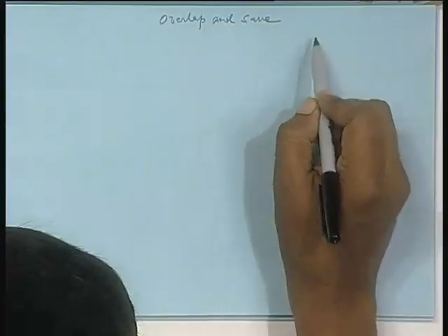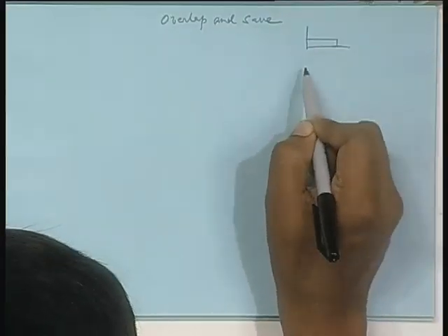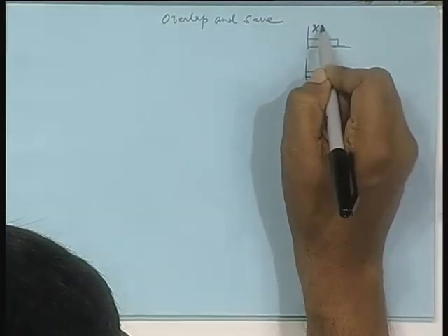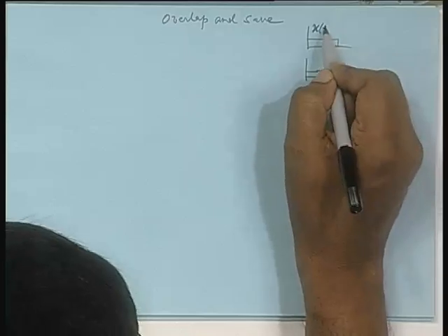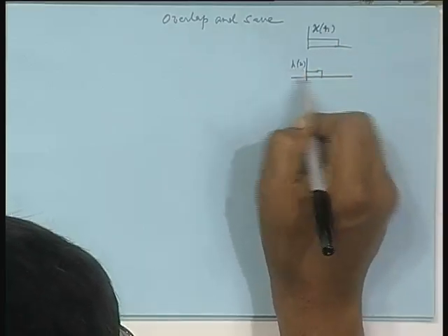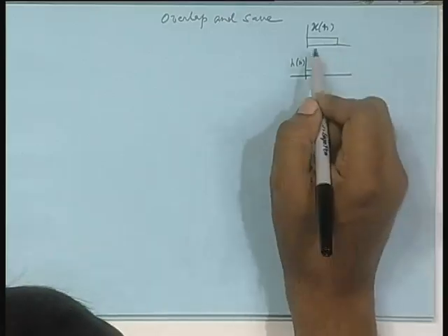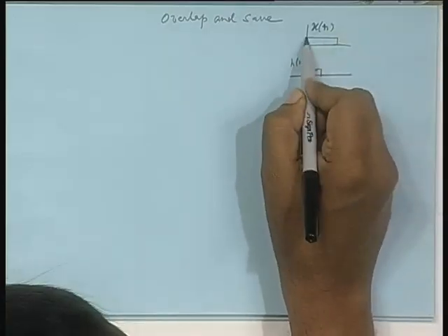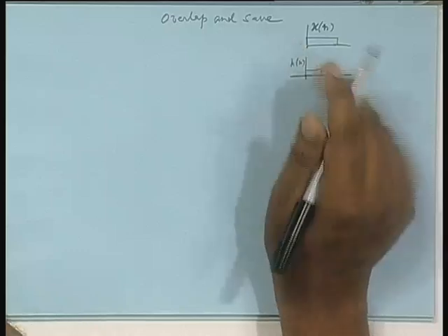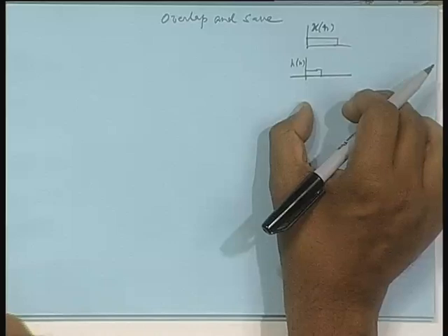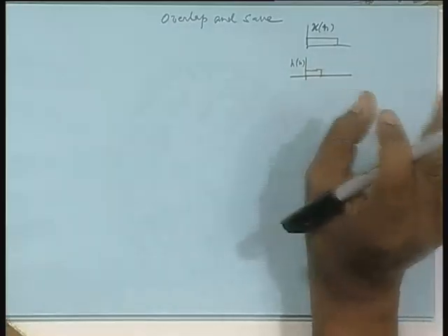Firstly, before I go into that, certain basic things of DSP, you see whether you can foresee. Suppose there are two sequences, one is here, another is here. You call it say x n, and you call this h n. You get a convolution. See, I have drawn it like this, that is causal. It is not necessary that they have to start at the origin, they can go beyond to the left also. My result does not depend on this shape, just two sequences. If you convolve, you get something. We know where it will be located and all those things.